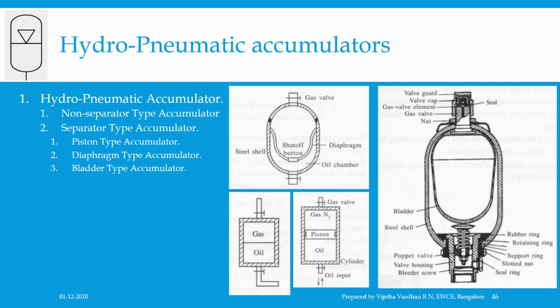When the oil in the accumulator is spent or utilized, its volume reduces, and hence the pressure of the oil in the accumulator. And this allows the bladder to expand, reducing the volume of space for the remaining oil to occupy, and hence increases its pressure to the initial value.